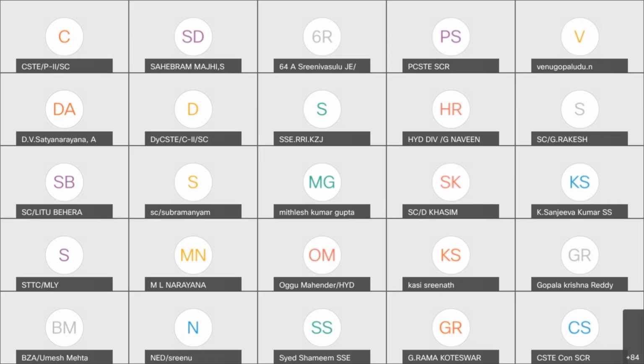In the track circuit area in the point zone, sir, we are using series and parallel connections. In the point zone area, from nose crossing to tongue rail, some tongue rails are parallel. So when the PWI wants to remove the tongue rail to nose crossing rails, the point will not get dropped, sir. So that may be taken into consideration. If we try series connections, it will be better, sir.